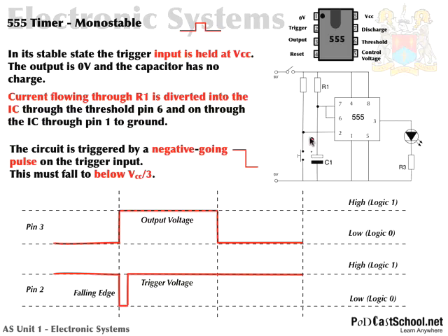Well, if you think of, like I said earlier, this little portion is a potential divider. Okay, it just so happens that the bottom switch is, well, if we think of it like a resistor, obviously it's got a very high resistance when the switch is open and a very low resistance when it's closed. So when it's open, it's got a very big resistance.